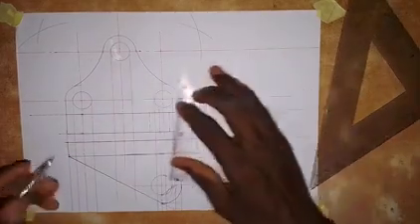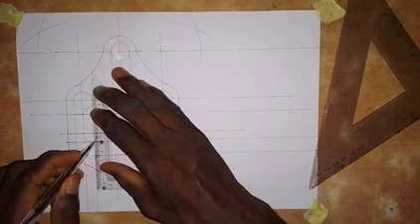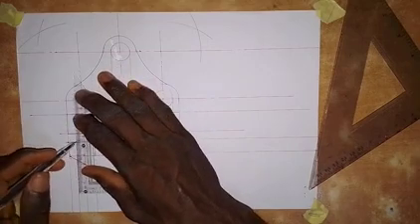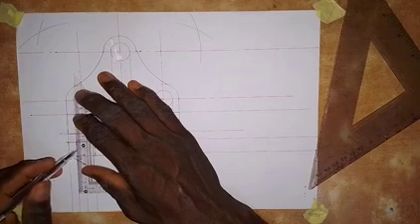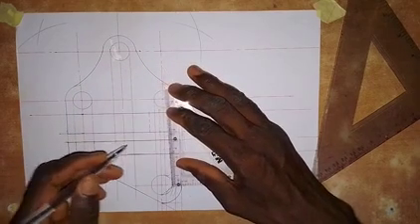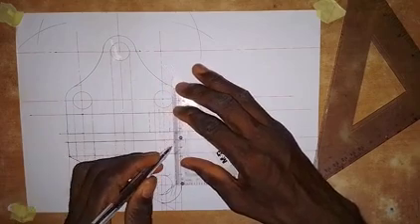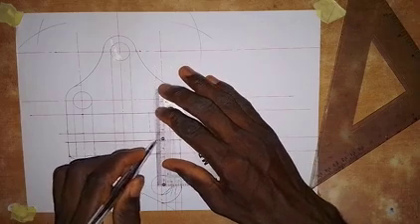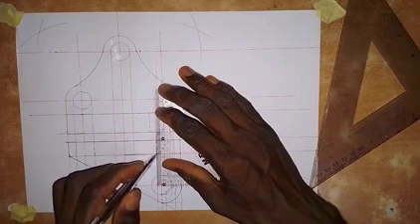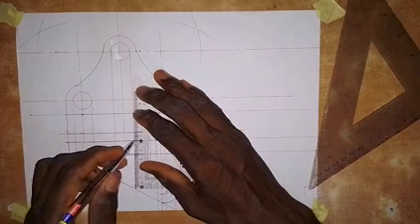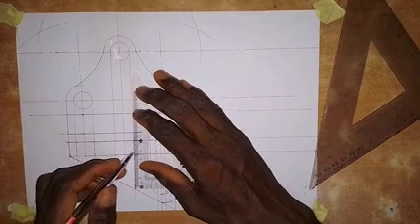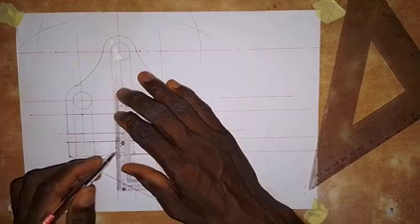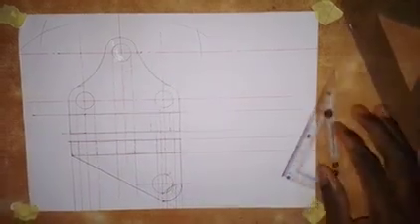Alright, so then in this plan, this line will be drawn with a short dashes line. So this is the hole that we have in the front elevation; in the plan, it is hidden. Also we do the same thing here. For this particular hole, and this also, make it with a short dashes line. Then the same thing applies to this. So make it a short dashes line in the plan, so it is hidden from us in the plan. Alright, so this is what we have for the plan.